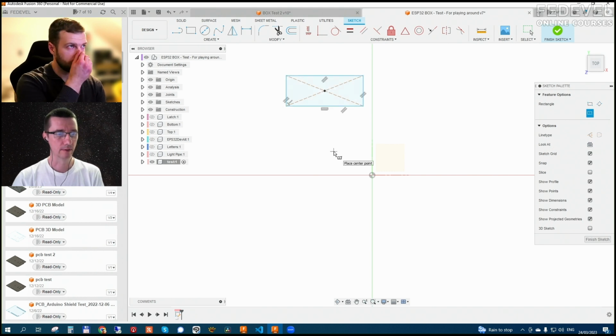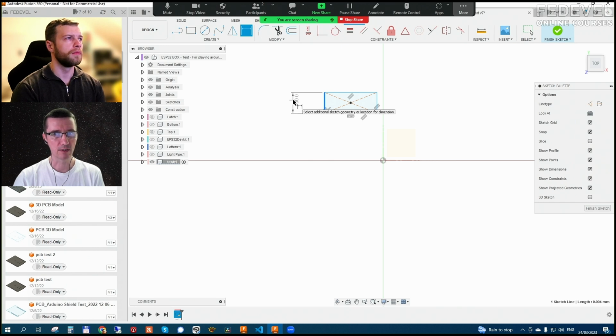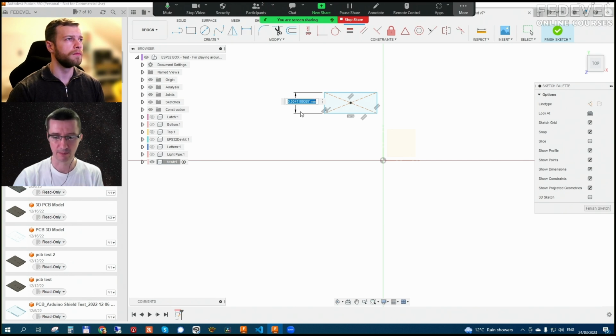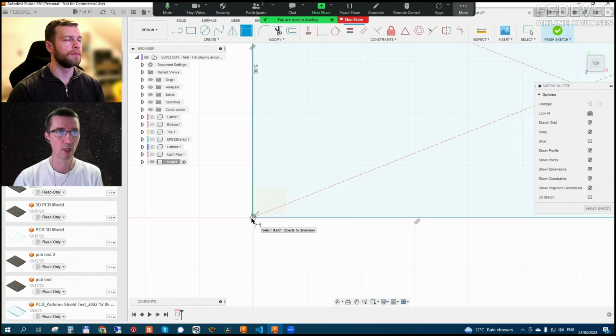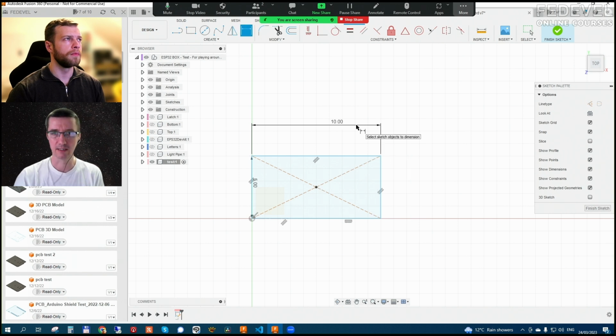Now you can write the dimensions directly, but I'm not going to do it, because you can always do dimensions this way. Click here and you can just draw it. Right now it is telling you the dimension of this line, but when you click, you can rewrite it. For example, 5 millimeters, and it will change. This is super useful because you don't have to keep measuring and drawing. You can just select it, and let's say this unit is 10 and it's 10.